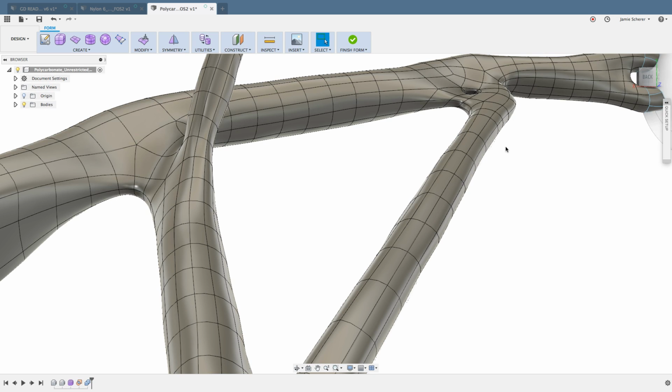But just the same, as you have more and more of those edges in really close proximity to each other, you're forcing it to make big curvature changes in a small space, which is where you start to see some of that chattering or that unsmooth edge that we had before. Now, maybe that's not enough. I can continue reducing the amount of edges that we have here. I'll delete them, and again, you'll see further still, this will become even smoother.